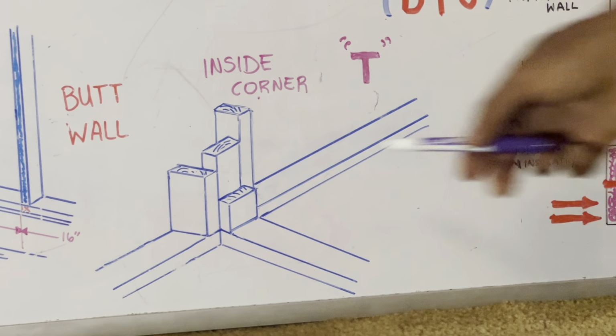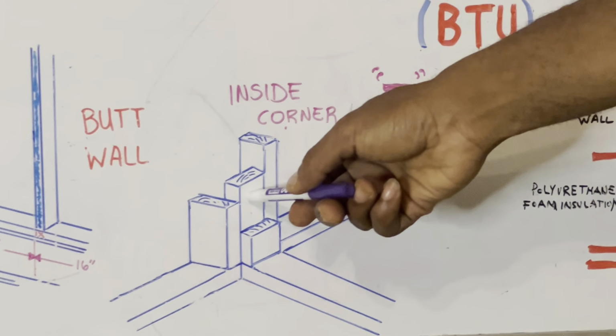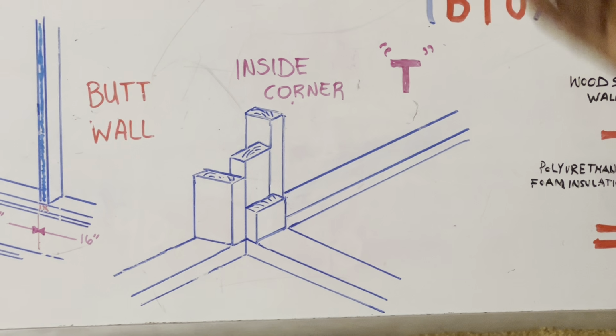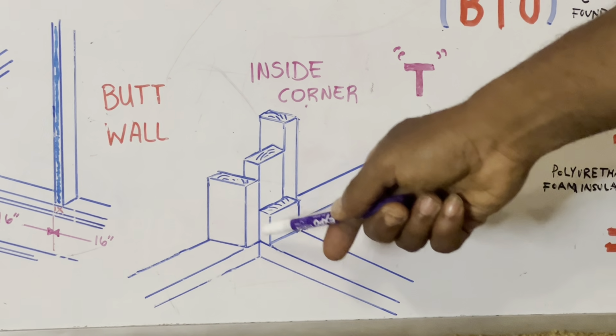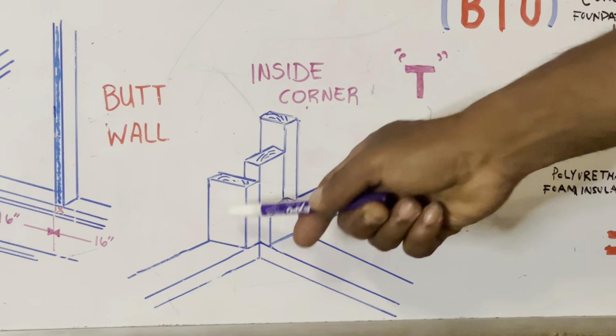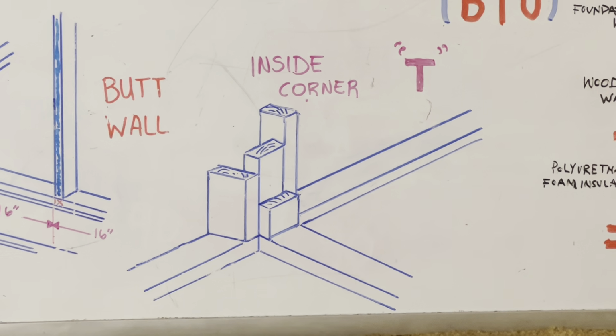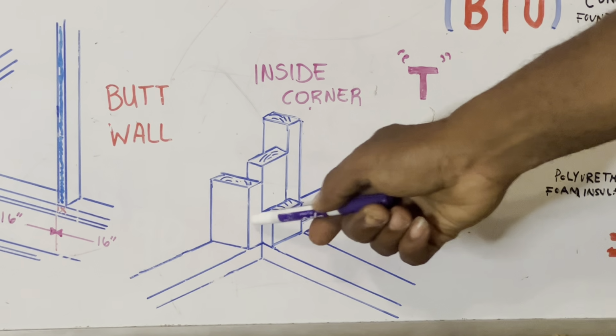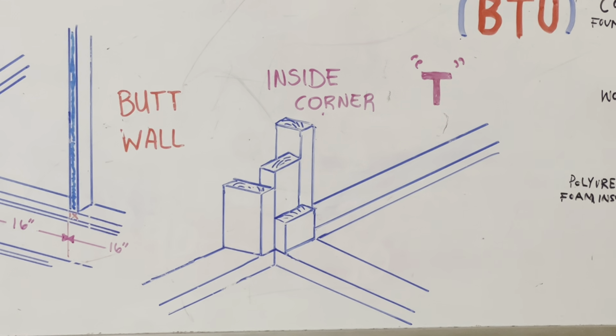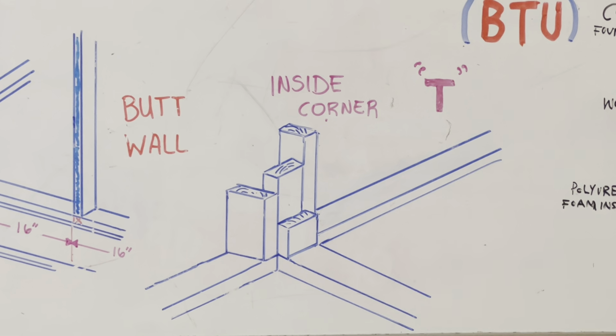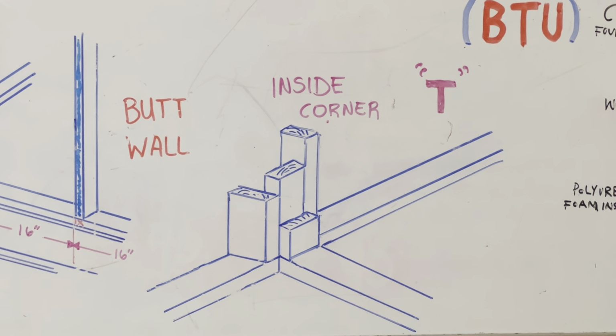Okay. So you can do this like this, a 2x4 that's facing flat. And you're gonna have two 2x4s on either side of the middle 2x4. That's what's gonna provide you backing for your sheetrock. Okay. Your interior wall covering. Okay, all right, that's the U-shaped one.